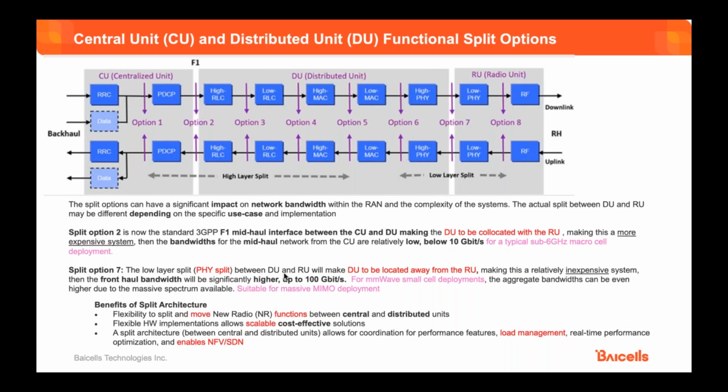Yeah, this slide is important. There are 3 functional units when it comes to RAN in 5G. It's divided into radio units, distributed units, and centralized units. These are according to the OSI layers. You have the physical layer, which is split into low physical and high physical layer. And then you have the network layer, and then you have the RRC, which is the TCP/IP layer. Depending on the split, you will realize different hardware and different functions. I'm going to focus on just 2 splits here, option 7 and option 2.